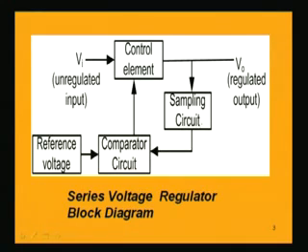This circuit is basically made of different resistances, and this sampling circuit feeds back a portion of the output voltage into a comparator. Now a comparator compares two voltages. The voltage which is coming from the output through this feedback circuit, which is a sampling circuit, is compared with a reference voltage. So there is a reference voltage being given here in the comparator circuit.